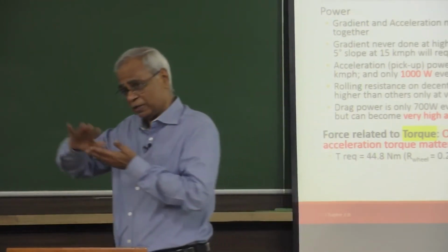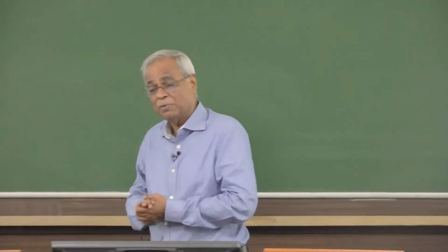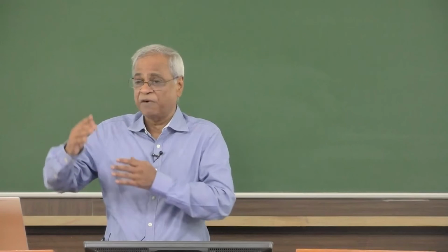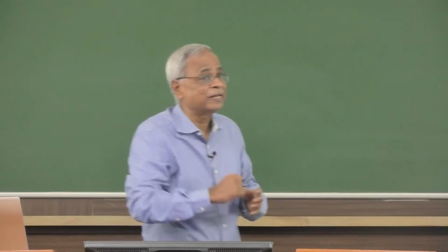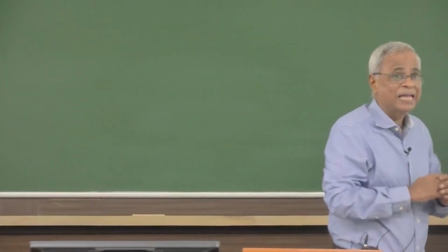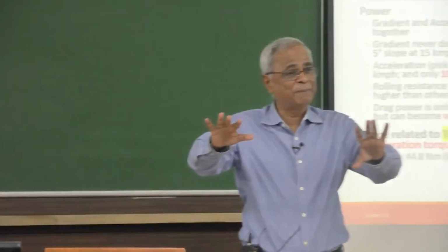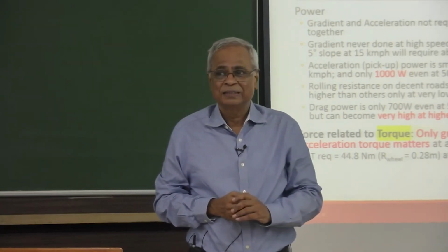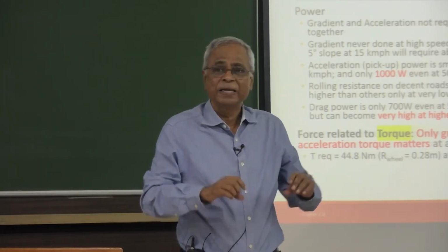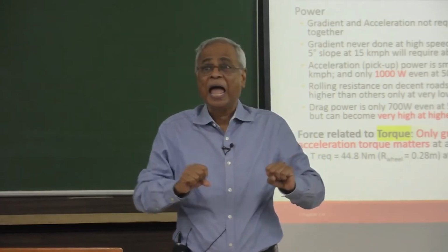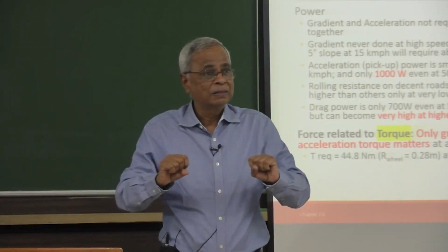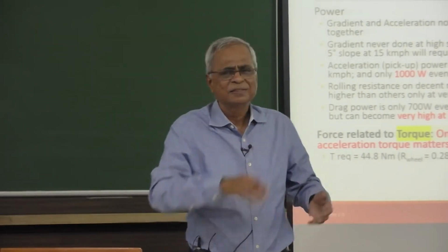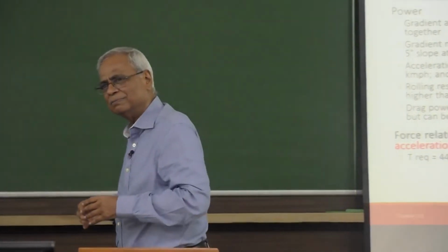If, on the other hand, I want 90 kilometer per hour, I will require a motor which is 5-6 kilowatt with peak going to 8-9 kilowatt. And that is a distinction that you see today in the market in India. You will see that there are vehicles by Hero, Ampere, which are 30 kilometer, 35 kilometer, and they are 50, 60,000, 65,000.